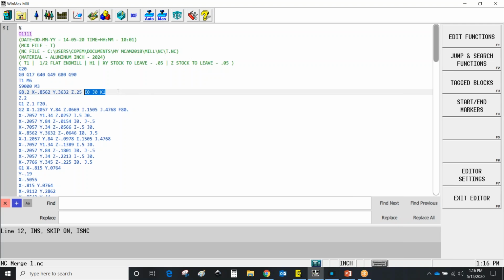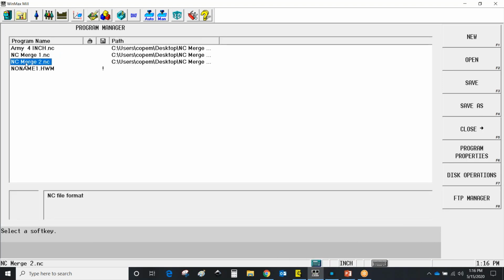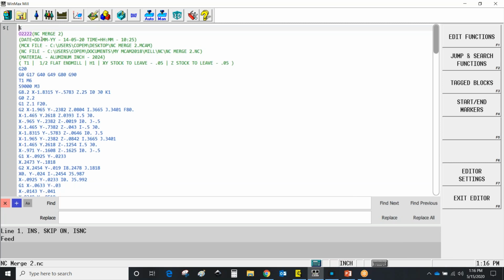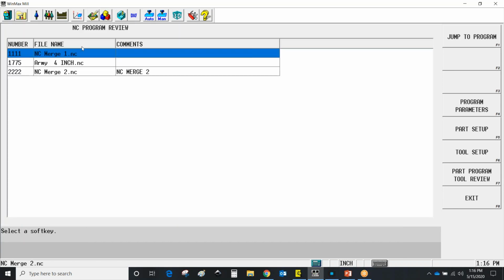So this is the only hand editing that I had to do to the regular 3-axis posted program to make it work. And then of course I had to make sure I had a 4-digit number up here at the top and an M99. And then I was able to use this in a multi-axis program and put it around the part. The next one we have is just another standard 3-axis program. Again, I hand edited that first position with the G8.2 and the IJK.